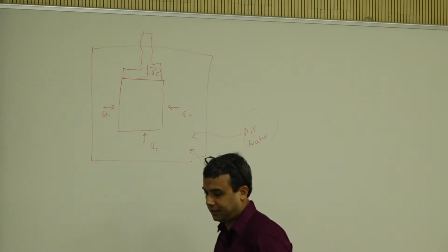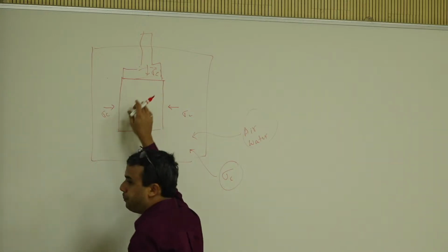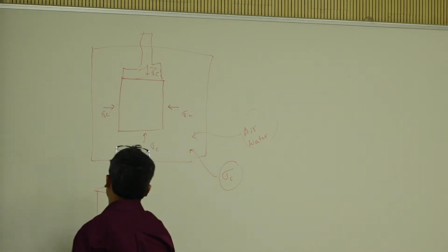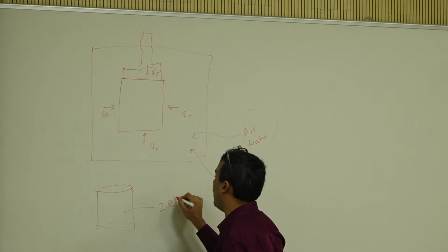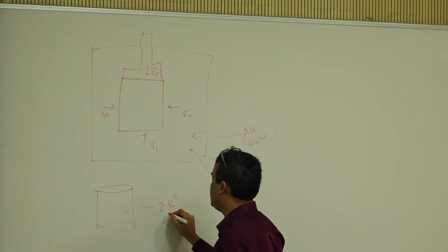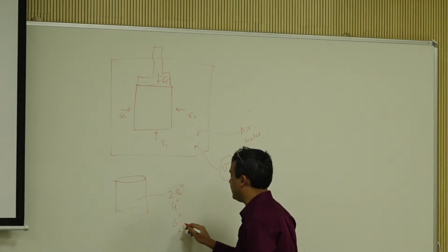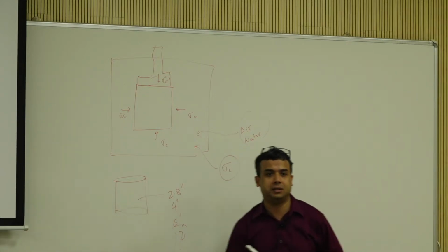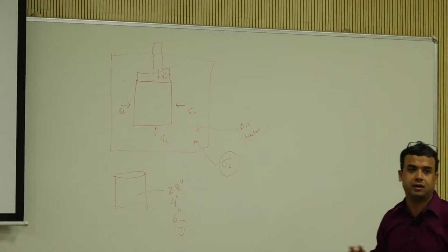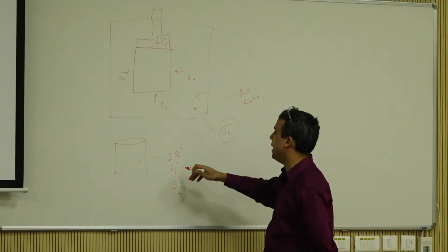Triaxial testing is done inside a chamber, and then you fill a sample. It is usually a cylindrical sample. If you're working with fine soils, you can have diameters in the range of 2.8 inches, 4 inches, 6 inches, up to 12 inches is what I have tested in my lab. So it's 12 by 24, which is like 300 millimeter diameter, 600 millimeter samples. So this is railroad ballast and stuff like that.